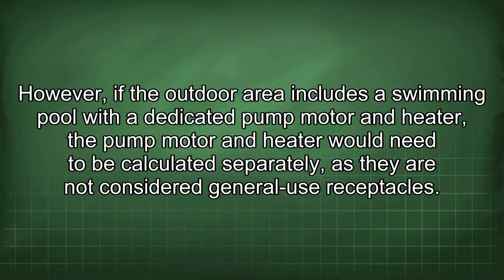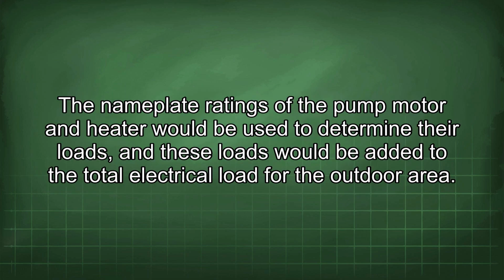However, if the outdoor area includes a swimming pool with a dedicated pump motor and heater, the pump motor and heater would need to be calculated separately, as they are not considered general use receptacles. The nameplate ratings of the pump motor and heater would be used to determine their loads, and these loads would be added to the total electrical load for the outdoor area.